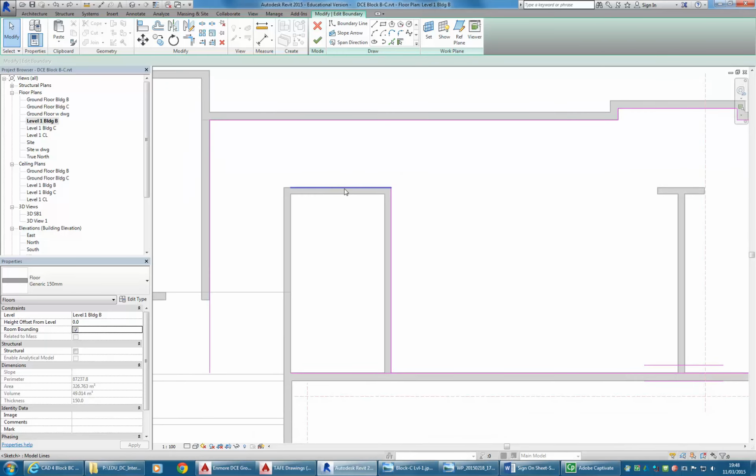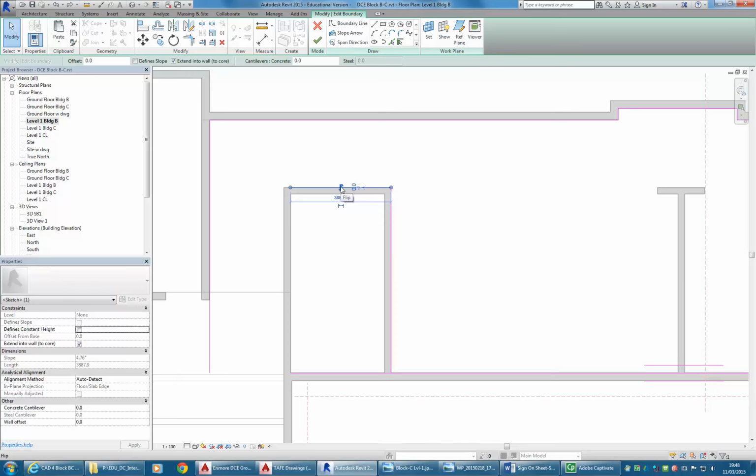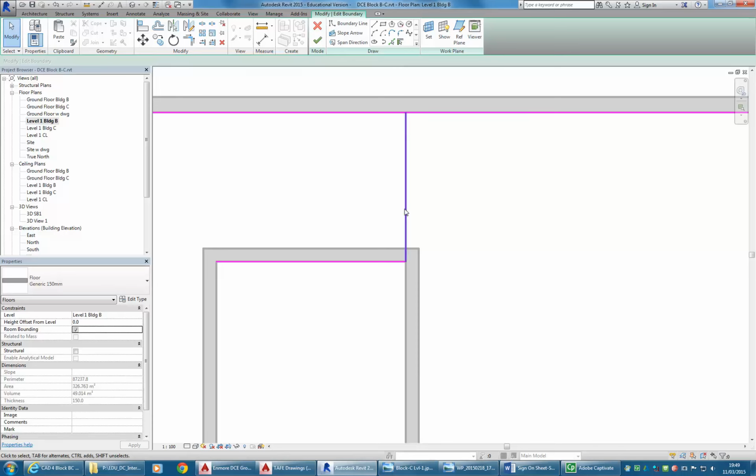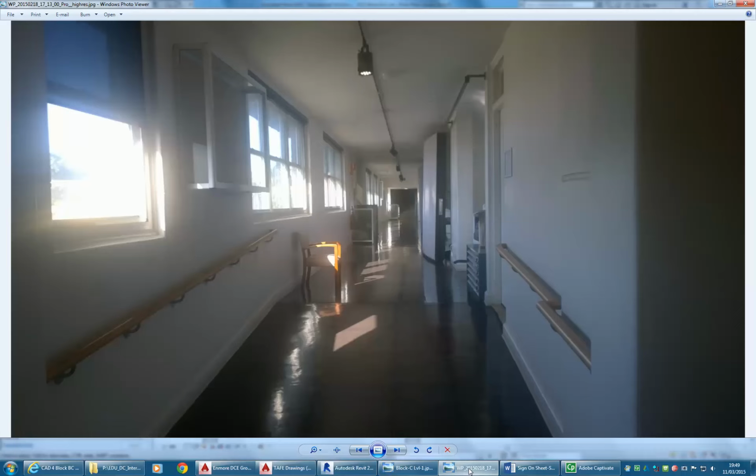So there, we could do a separate floor, but I think it doesn't hurt just to flip that onto the inside, drag this line. An interesting thing when you make walls, also make lines or edges to your floor using pick walls, you can still drag them away from the wall that's been used to create it. So I think it's really interesting. That means that this line now no longer follows this wall, but if I move this wall, that line's still going to go with it. And that's what it should do, because logically the edge of that floor should basically follow the inside of this wall. So you can see there, actually probably it's on the other side.